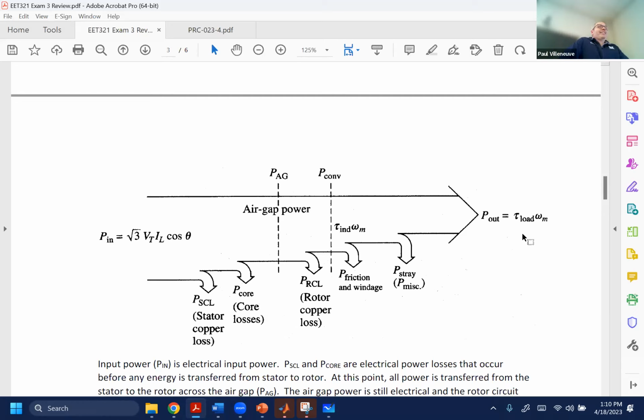You don't know about that? Yeah. Okay, a couple people said no. You may want to double check that. Every 50 miles, because aluminum is a soft metal, you're supposed to retorque them just to make sure it's safe. If you haven't done that, you need to do it the first time, and then after that, change your tires, right?